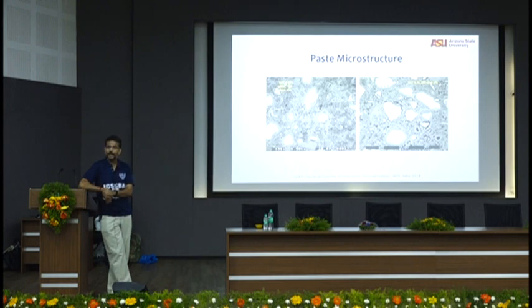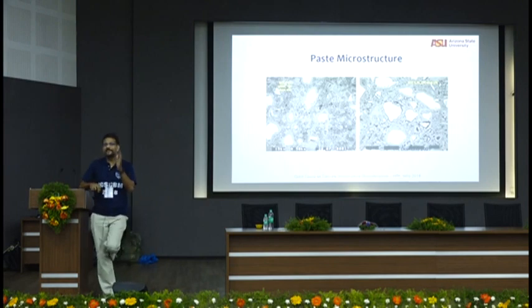A lot of people do that. I have 90% degree of hydration. So what? You've put in a lorry load of water and therefore you have 90% degree of hydration. You have bad concrete. So degree of hydration is never ever a measure of property. It is just a tool for you to find out how much cement is hydrated. That's it. It has no relation with property.